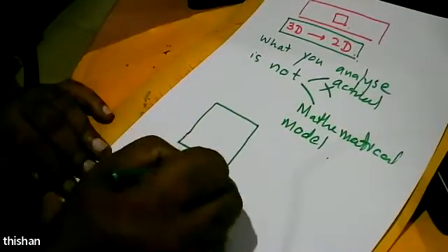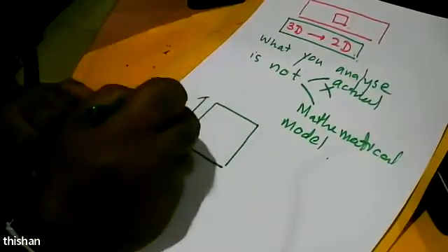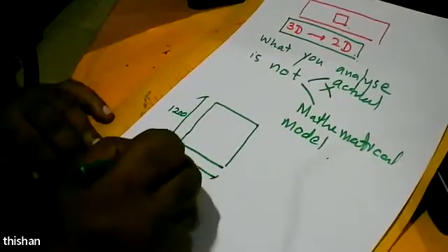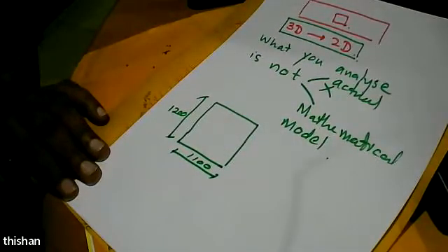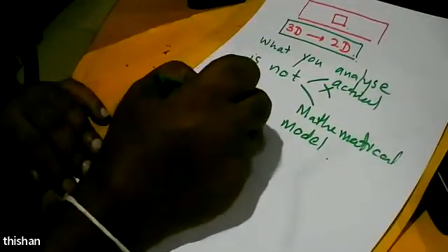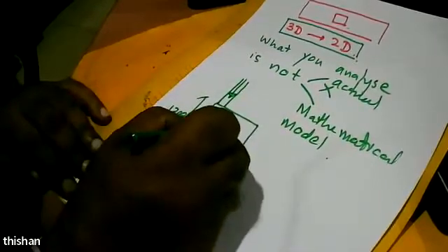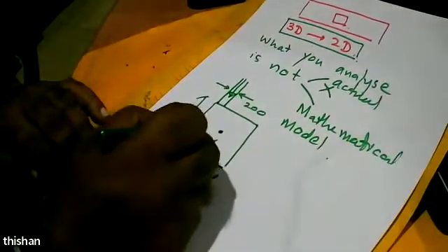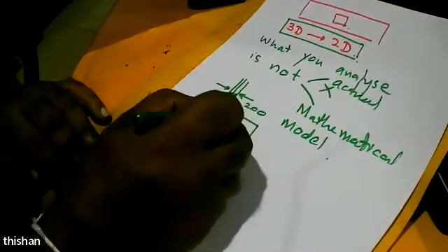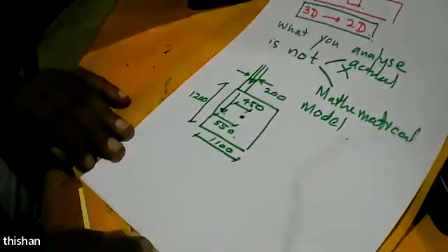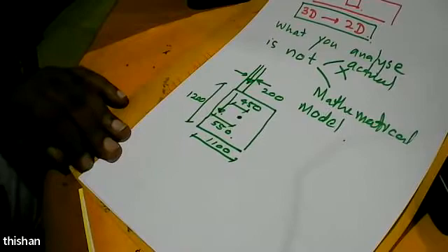that we have a beam, a large beam, say 1200 by 1100. For some reason we have selected a depth of 1200 and we have made it wide, say 1100 millimeters. And let's say we have a shear wall coming and resting here on the side. The shear wall thickness is 200. So here you get 550 millimeters, and the center of the shear wall is at 450 millimeters. So how do you model this beam?